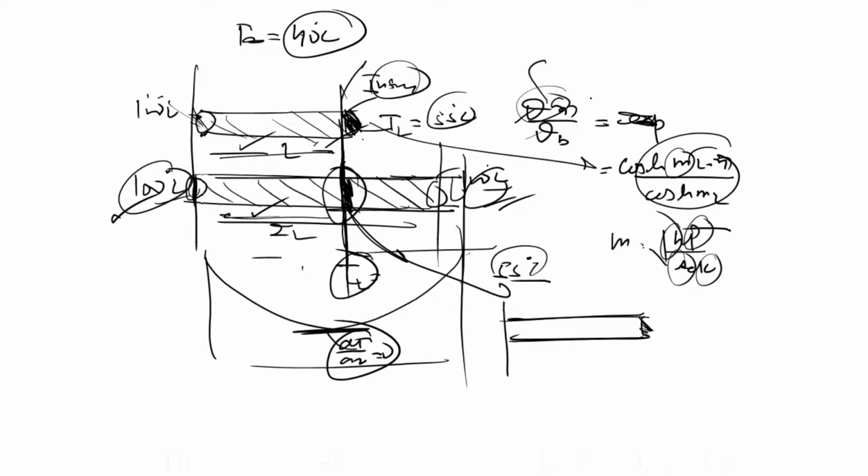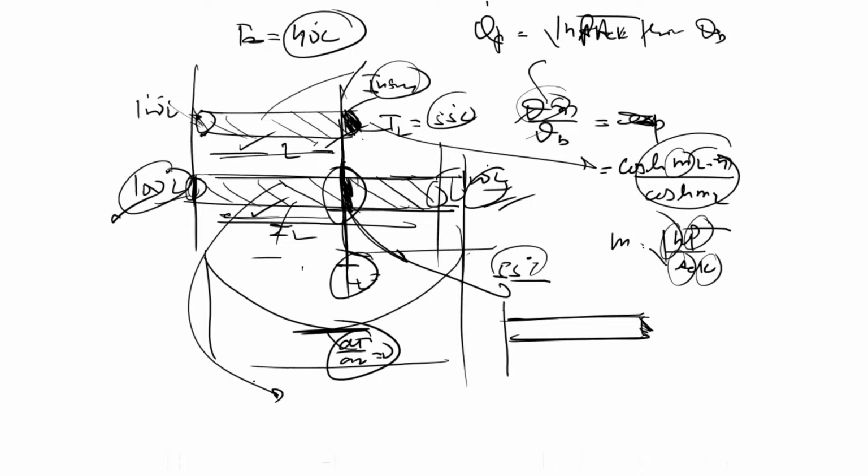And if you want to find the heat transfer through the fin, you can directly find Q fin equal to square root of hP A_c K into tanh mL into theta b. No formula. And what is the heat transfer through the second fin? It is twice of this, because half from this and half from this. Symmetry is there. Then you can make it twice. That will be the answer.